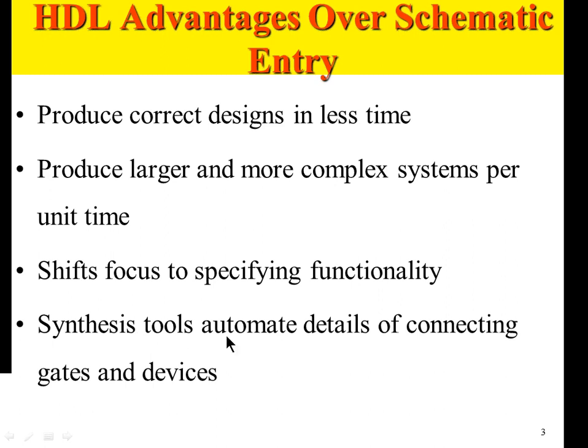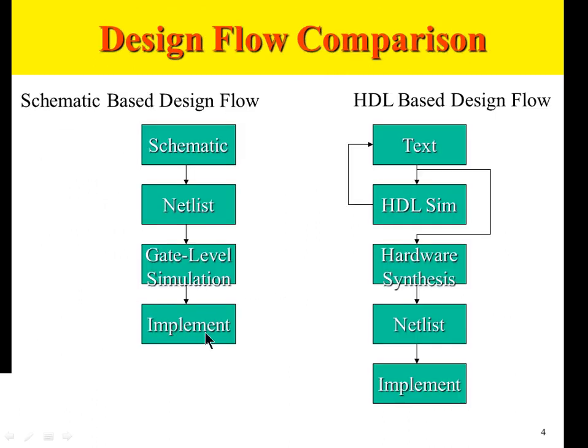That's where the focus is with Verilog. The synthesis tool automates the details of connecting gates and devices. Once the Verilog functionality is defined properly, it is given as an input to the synthesis tool, which will then convert that design to a gate level netlist, and the gates and the interconnections between gates will all be taken care of automatically by the synthesis tool based on your Verilog design. So you save time on that.